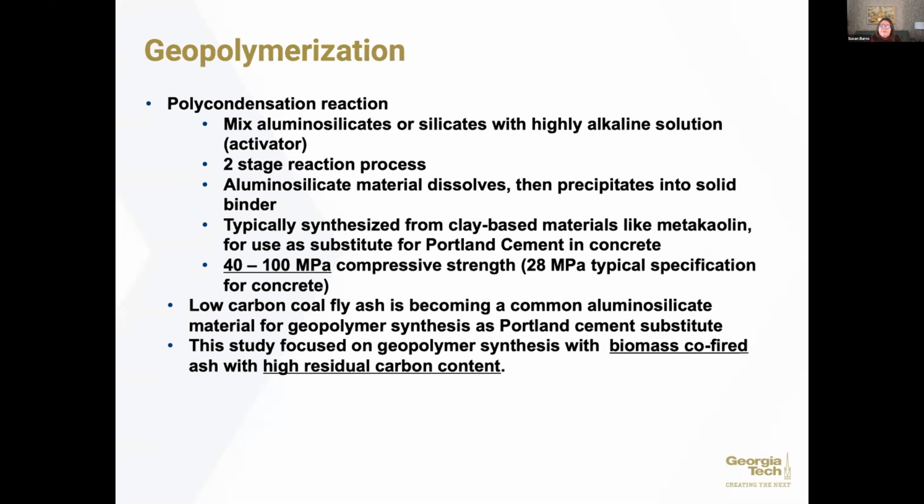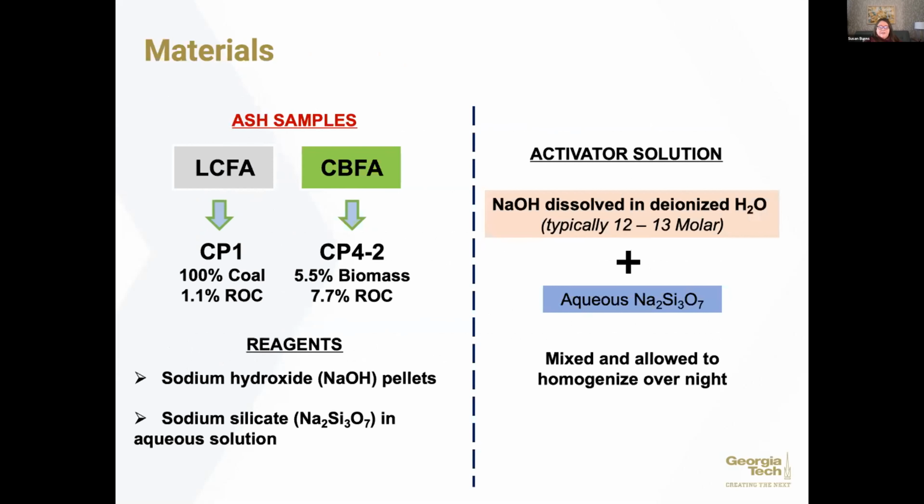So what you'll see here is that we tested this not with the low carbon fly ash, but with biomass co-fired ash and with the high residual carbon content. And you'll see here the steps in the process. Essentially, we took these ashes and we combined them with the reagents of sodium hydroxide and sodium silicate. And then we've got a sodium hydroxide solution that we're going to dissolve them in. Okay, and so we mix them, we allow them to sit overnight.